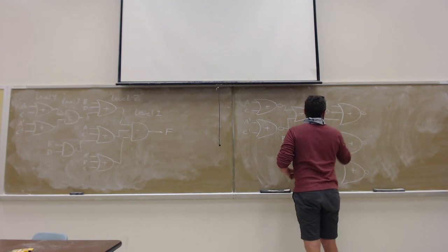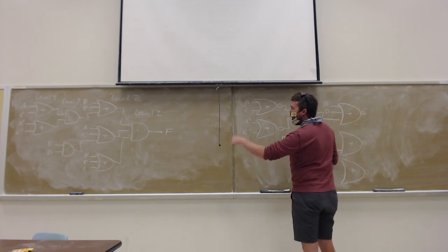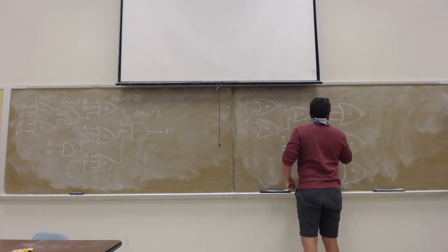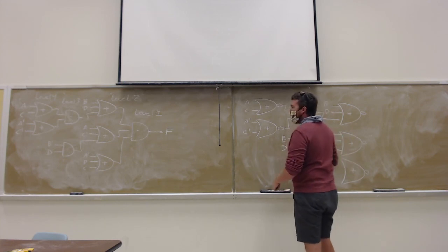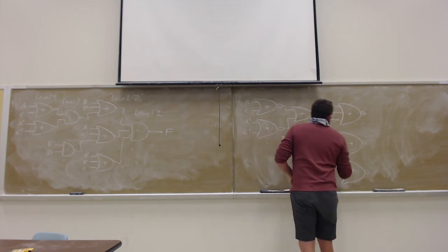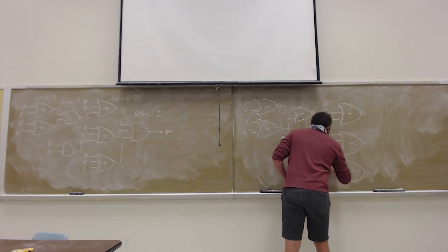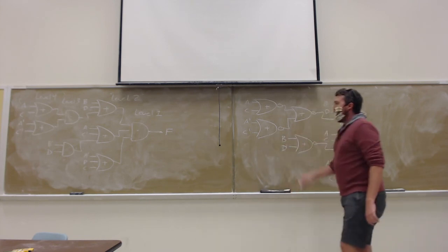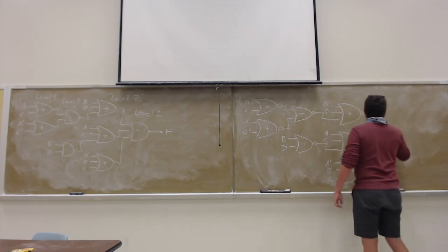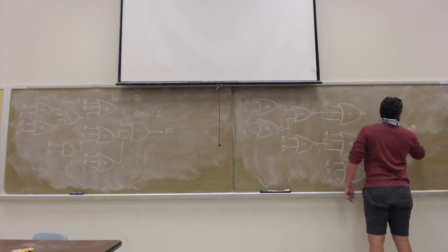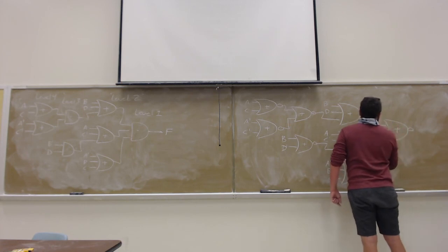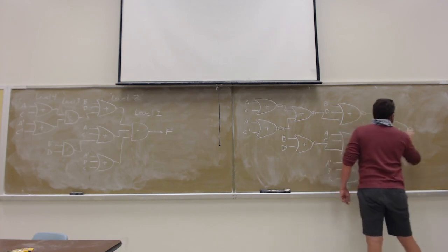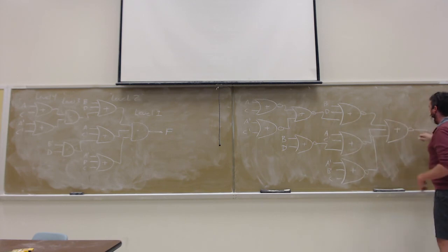B stays B and D. And we have A and C prime, so A or C prime is going to stay A or C prime, then A prime or B prime or C is going to stay A prime, B prime, C. And then finally, the last gate is converted to NOR. It has no single input literal, so there's nothing to change, despite the fact that it's level 1, which is an odd number level. And that gives us our output F.